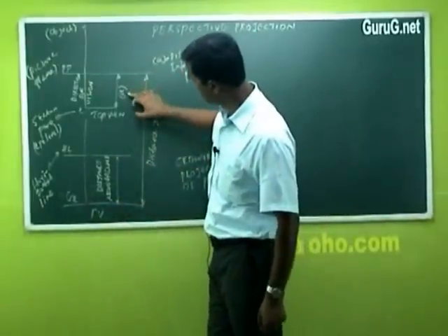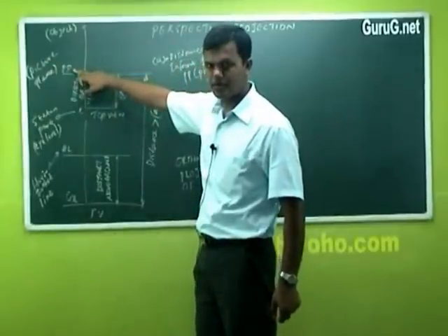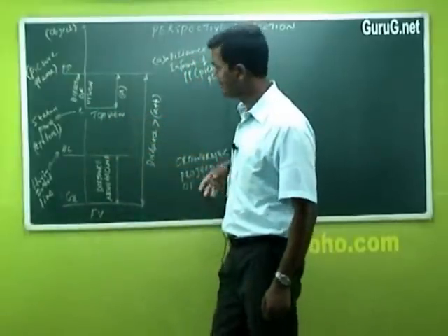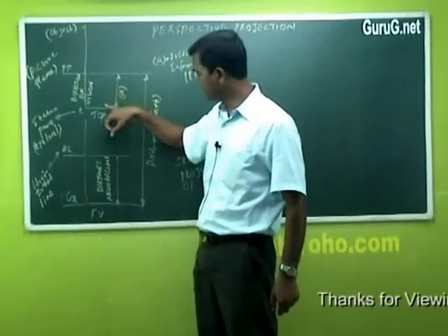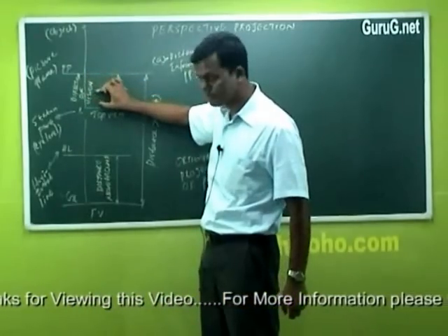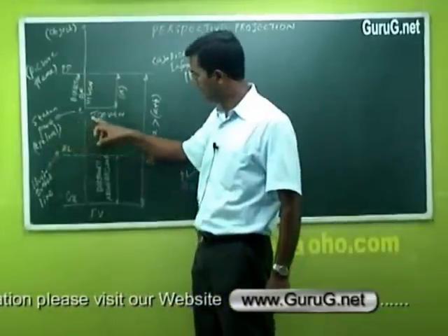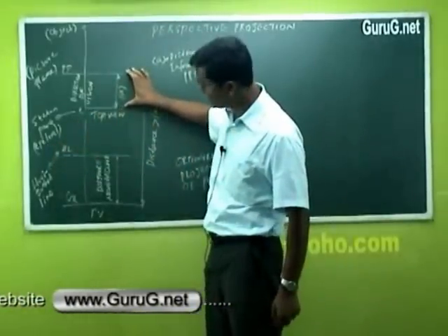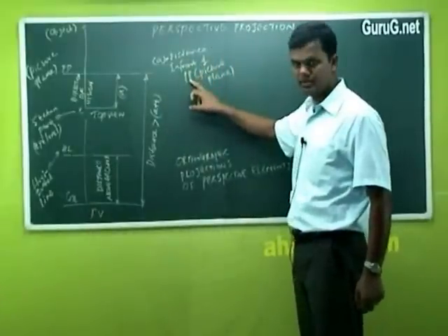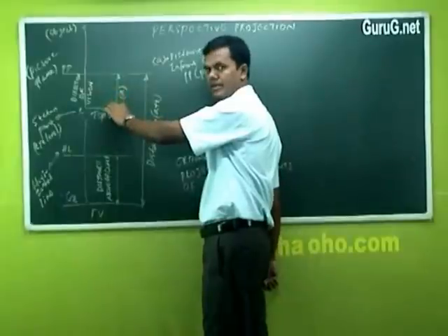And remember, this small a which I have indicated here. PP means picture plane, the short form. You'll be writing PP, or HL for horizontal line, etc. Some of the points like this are the elements. Below the PP, the picture plane, you have the direction of vision, that is point E. This point is called the station point or eye level. This one has a distance of small a. That a is known as the distance in front of PP. The value is the distance in front of PP. It will be given in the question. This we have to indicate.